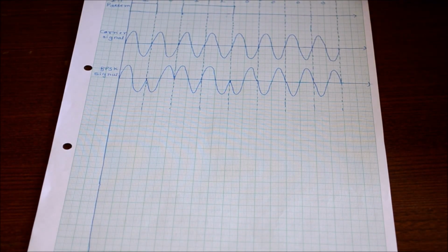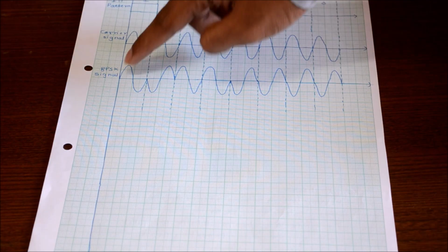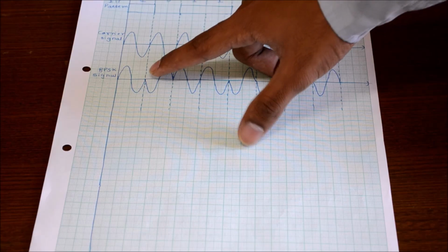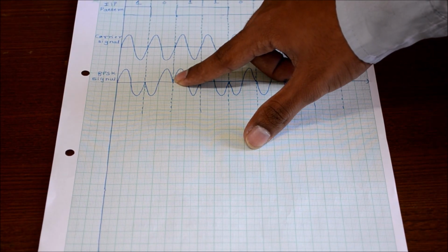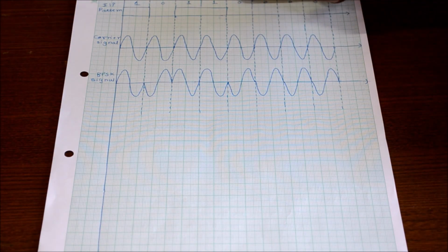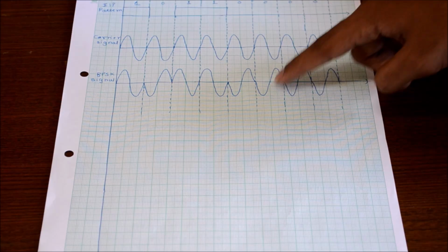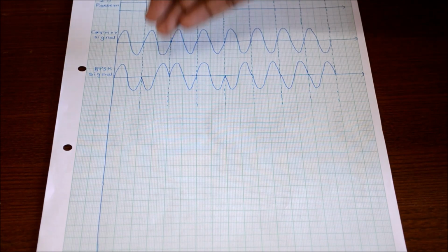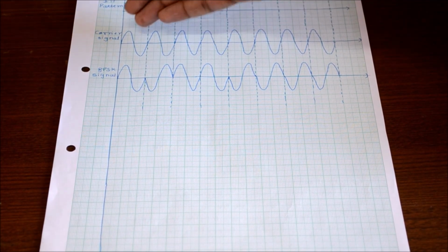As you can see, I have shown the input pattern here, that is 10110000, and I have shown a carrier signal here. Now as you can see, for bit 1 the signal is as it is, that is it is having 0 degree phase shift. Now when the bit is 0, it is having 180 phase shift, that is it is inverted. Again for bit 1 the phase shift is 0 degree, and again for the remaining 0 bits it is 180 degree. So you can say that for logic 0 the output will be the inverse of the original carrier signal.